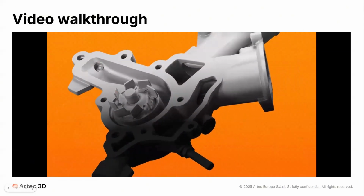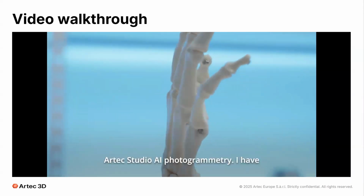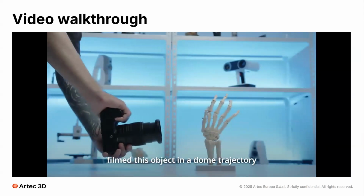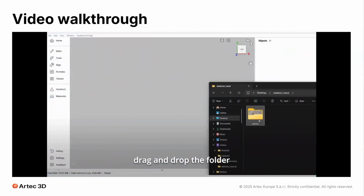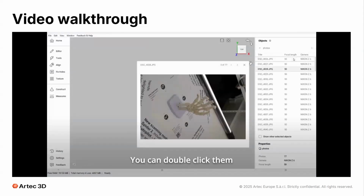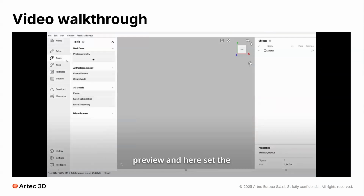I'm going to use this skeleton hand, which was featured previously, for the demonstration. First of all, I'm putting it in orientation. I'm making sure that it's evenly lit, and I'm using a camera in order to capture the images in a full dome around the object. Once I have captured the images, I am importing them into Artec Studio. Here you see that they are appearing in the workspace, and you can double click the entity to go through each one of them.